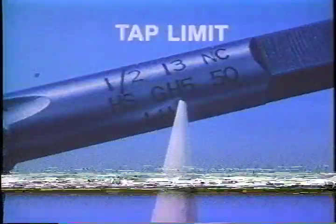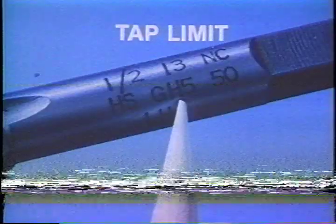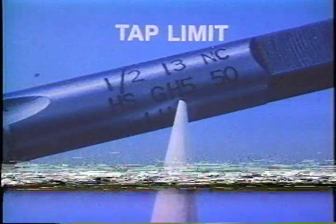The accuracy of the thread limit is also marked on the shank. For example, this H5 marking corresponds to the H5 in this table of values. It indicates that the tap is slightly bigger than the standard, and the threaded hole it makes will have a looser fit.